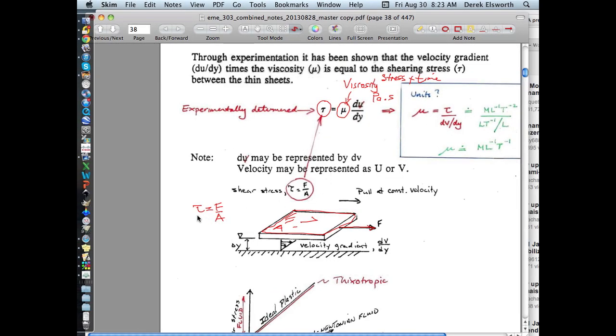So shear stress we have, which is what we need. The shearing rate is the velocity of this plate and the appropriate boundary conditions. The idea is that a molecule of fluid sitting next to the plate is physically attached to the plate. So when you drive the plate at some velocity, that molecule of fluid travels with it and drags all of its friends along with it.